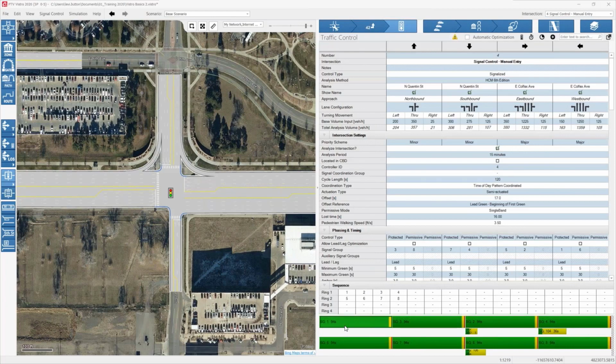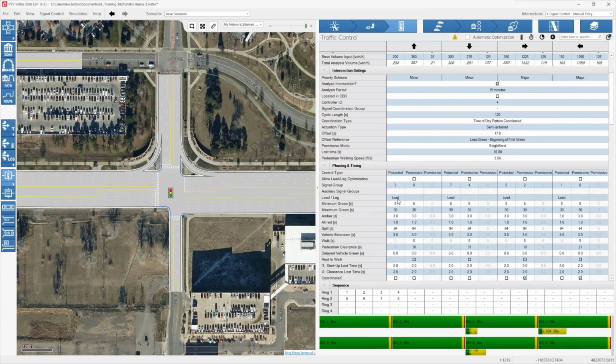You'll notice that it's putting both the left turns ahead of both of the through movements, and that's because phases 1 and 3 have been set to leading, and I haven't set a barrier yet. So how you set a barrier is you just hover over this gray bar that separates the 2 cells, and you left click on it one time and it'll add a barrier. And you can see that it'll automatically snap these into the appropriate barrier group as well.